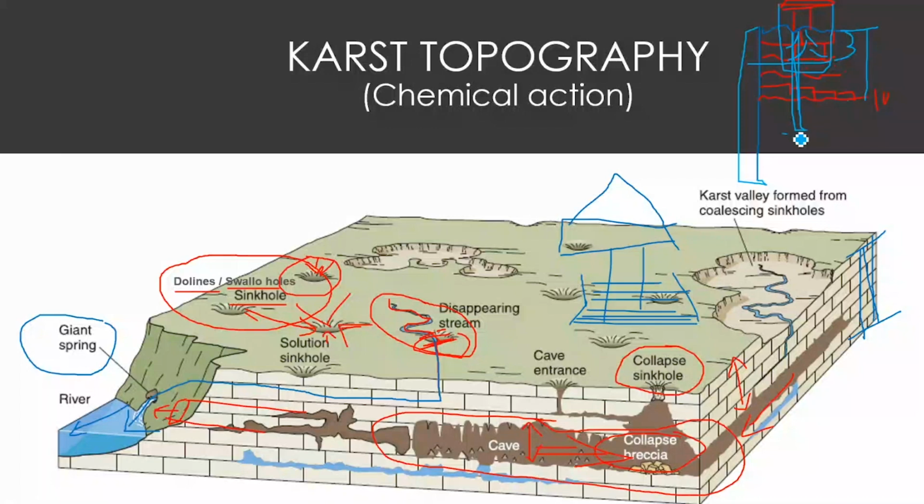If this rock is again the same thing, then we don't have any other option. We may have to entirely cut out all this rock type from this area and fill it with concrete or any other solid material. We need to go for ground improvement techniques. Compaction and all those things you use in a normal condition may not be possible to apply here. Rather, the only way we are left with is to completely take the area, remove the rock, fill it with a good rock or good soil, and then go for the foundation. Okay, so these are the different possibilities, but the key